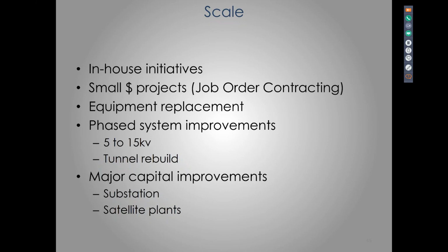Low-lying fruit with our LED lights, to our air handlers with the variable frequency drives, to our fume hoods that in some cases are exhausting out 100% of air. Can we scale that back? And you can see a huge savings then in your chill water bill, your electricity bill. So there's just great opportunities when you have a good understanding of what's taking place in the building. But you have to have the team that understands that.